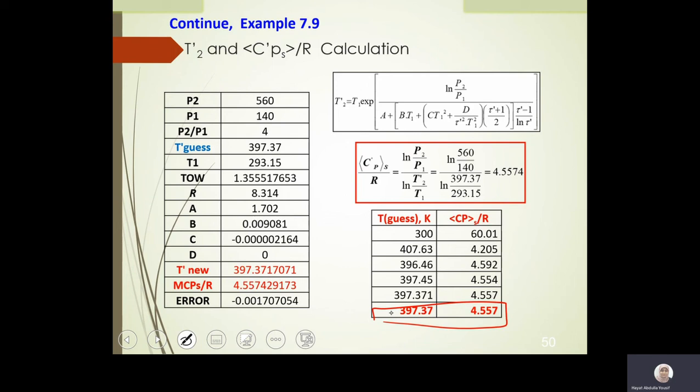The mixing itself has a significant effect on the answer, and that's why we cannot apply the nozzle equations. Although the usual equations for a nozzle apply, the mixing process is complex, and as a result, ejector design is largely empirical. Empirical means you can get the equation from experiments, and that equation is used to solve ejector problems. The nozzle equations will give deviations because of the mixing issue.